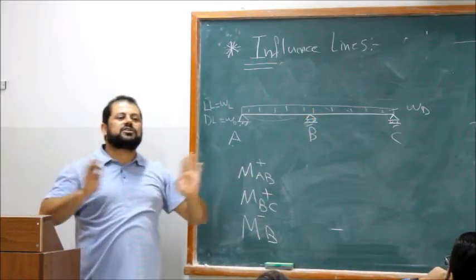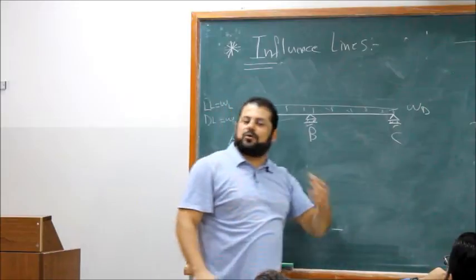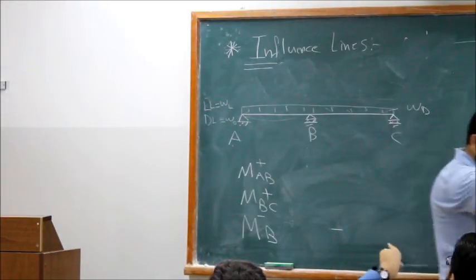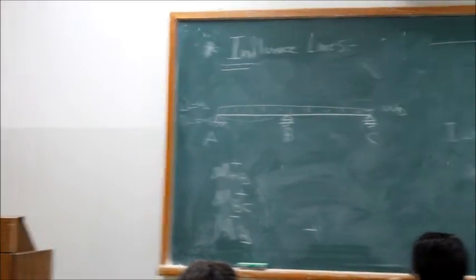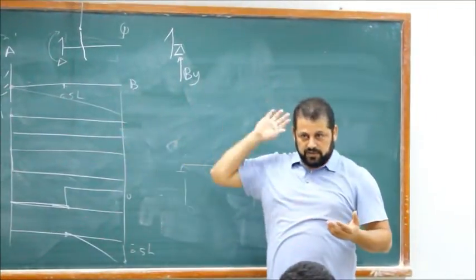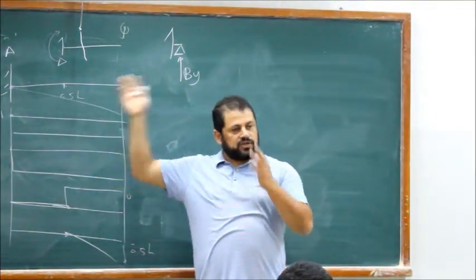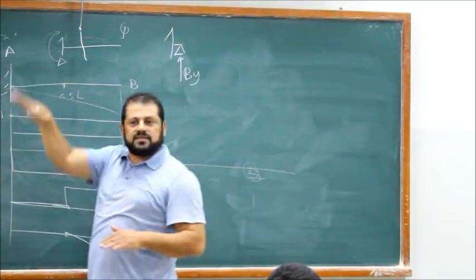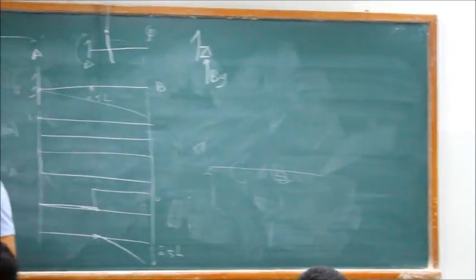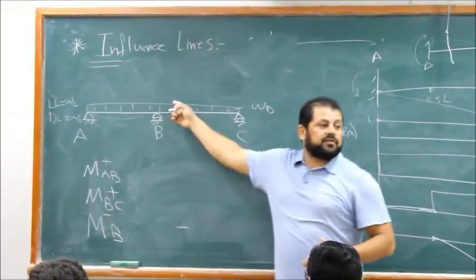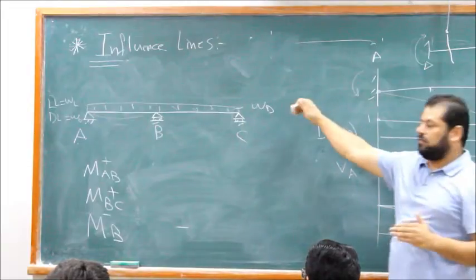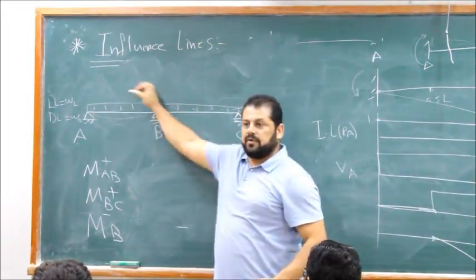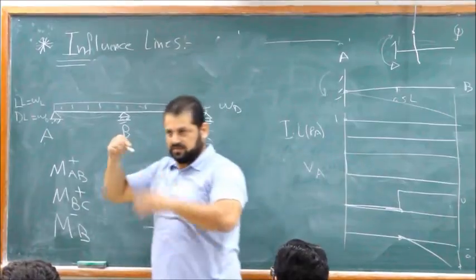So if you're talking about reinforced concrete, where do we place the reinforcement, the hadid? At the tension side. Why do you put reinforcement at the tension side? Because concrete is weak in tension and strong in compression. So we put reinforcement. Good? So you need to know what the tension side is. If you have positive moment, it's a smile, tension at the bottom, so the reinforcement goes down. If you have negative moment, sad, tension at the top, so the reinforcement is at the top. This is the design, just for you to know.